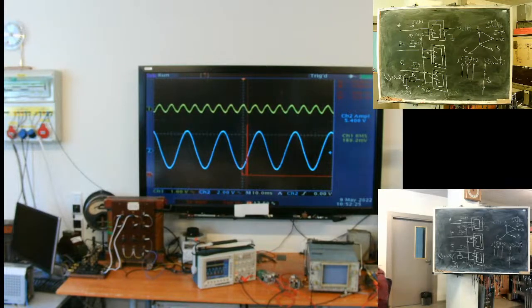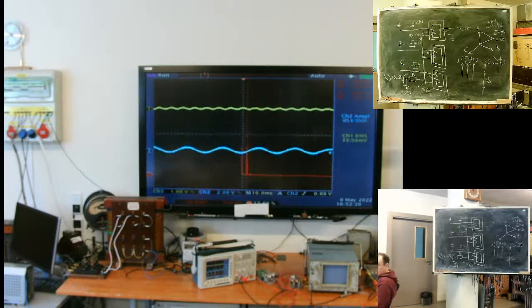We saw one of the effects of the distribution network. A 10 kilovolt network basically operates with isolated neutral. When a cheaper Y0 transformer is connected to this network, when voltage is near nominal, everything is fine, nothing special happens.